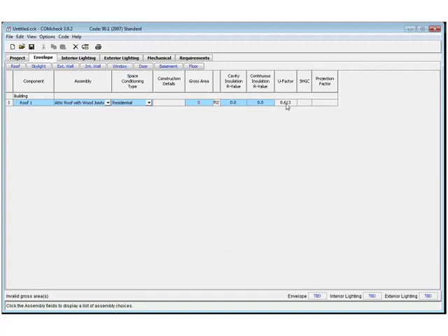But look at the U factor. It already has calculated, based on what I've entered for this option as an attic roof with wood joists. This is everything in that typical assembly, air films, framing, except for your square footage and what you're going to insulate it to. So let's put in some square footage here. Doesn't change the U factor yet. What will change it is the insulation being installed.